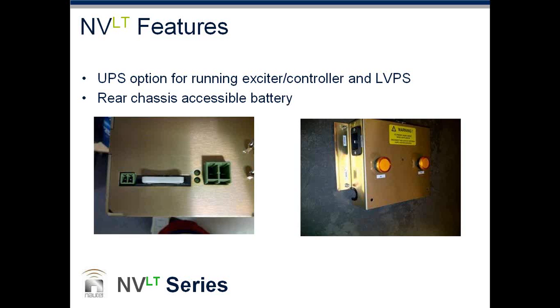Okay. The battery on the exciter is only used to keep the real-time clock working. So if it was to fade, then you've got to reset your clock, unless you've got the new NTP client running, in which case it'll set itself. And that's a good point.